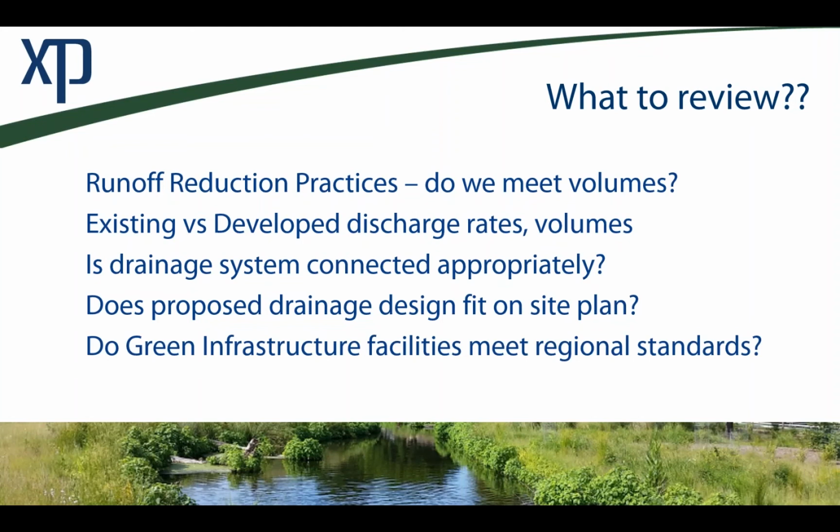Do the green infrastructure facilities, the stormwater controls I might call them, actually meet regional standards? You might have your own tools or spreadsheets, or older tools and spreadsheets by a city or municipality that maybe don't reflect the current standards, the latest releases of their documents.